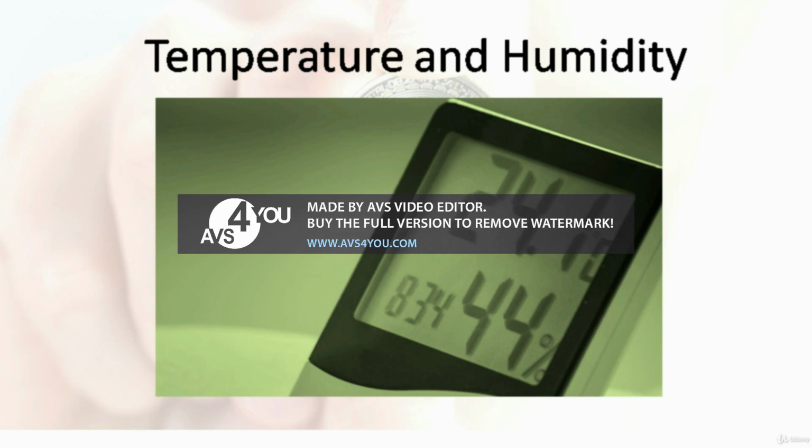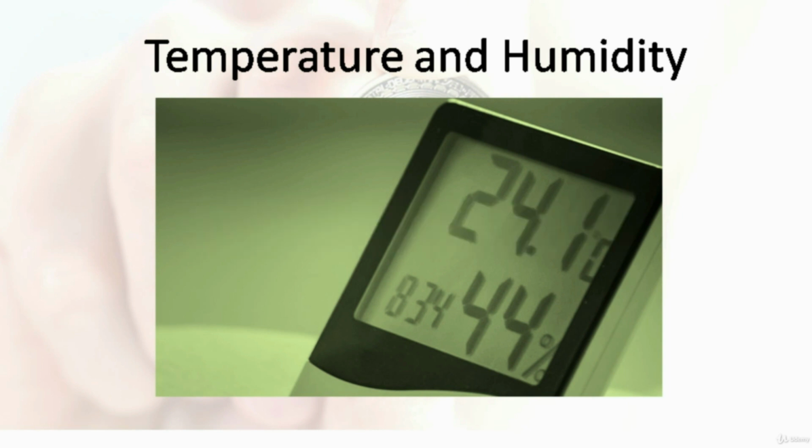I would recommend that at the intake vents of your rigs, you should install sensors measuring the supply air temperature. You should also set up multiple alerts that will notify you on your mobile device or something similar whenever the temperature or humidity rises or decreases to a point where the activity of the mining rigs is at risk. Furthermore, the environment that the rigs are in will start warming up in the event of a cooling malfunction, leading to a steady increase in intake temperature. Before you hit the limits of the mining rigs, you would want the starting point of the temperature rise to be low enough to allow you some time to get the cooling back online before any real damage can be done to your mining rigs.